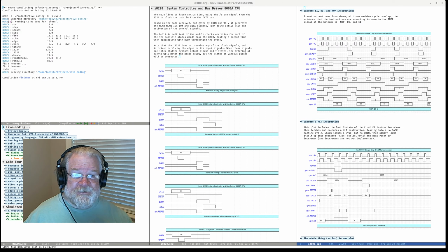So the FB is enable interrupts, so this raises the int E line. Yay! So next instruction comes on, and it's at address 1. We've already incremented PC to 1, so we come into this cycle. This is an M1T1 again, and we say sync, and it's another instruction fetch. Yay, A2.